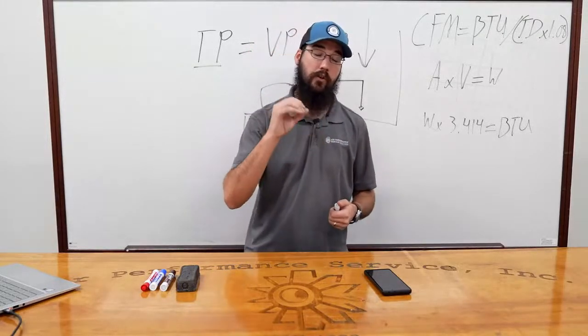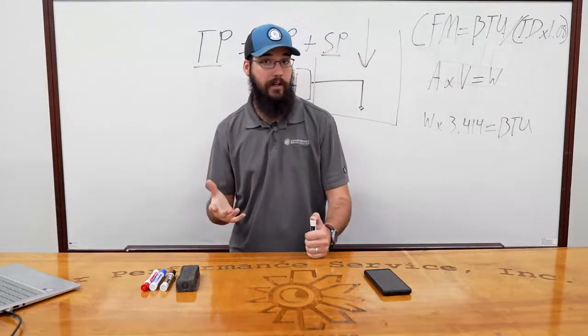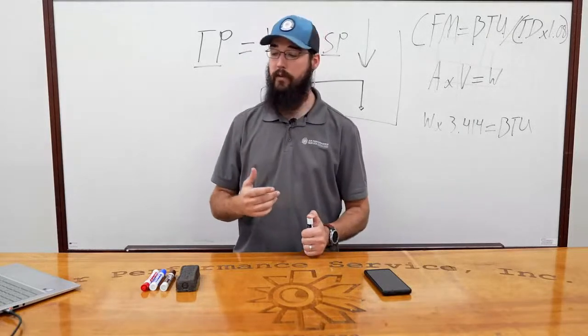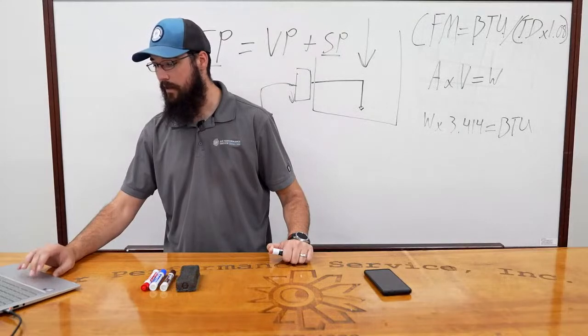Because another huge symptom of too much airflow would be high humidity. And that's a lot of times where those calls come from. They come from high humidity in the space.